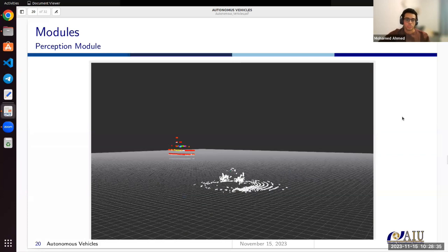Here's the LiDAR. We are trying to take the point cloud and make some modifications using maybe the IMU, because when you are, for example, on a boat, the waves will make the boat tilt a lot, and this will make your point cloud fluctuate a lot. So you need the IMU information about the orientation to correct your orientation, or fix your point cloud.